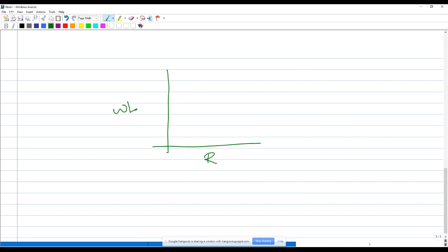So when it is away from the sample, that is a point over here, right? So this point indicates the total impedance of the coil inside the probe, which consists of both the inductive component, which is this one here, and also the resistance, which is here. Okay, so a combination of these two is the total resistance or the impedance of the coil when it is away from the sample.